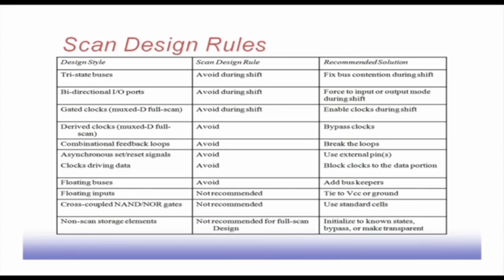Similarly, bidirectional input output ports. We have to force the input or output mode during shift. Somehow, we have to ensure that they become unidirectional. So, there are many issues that will be coming, which need to be corrected in the scan design process. And as I have already said, these CAD tools are available which will do these things.